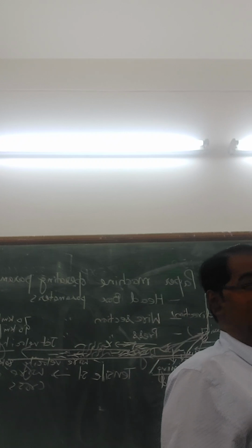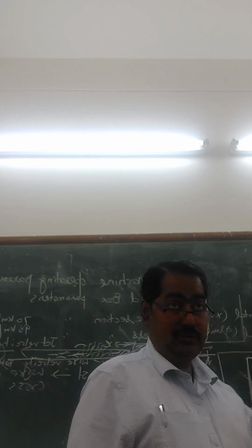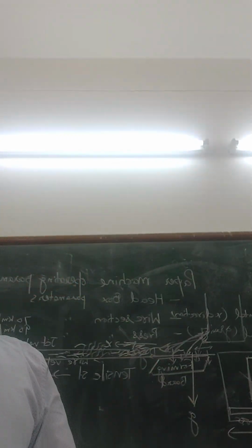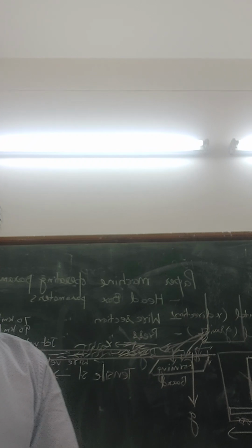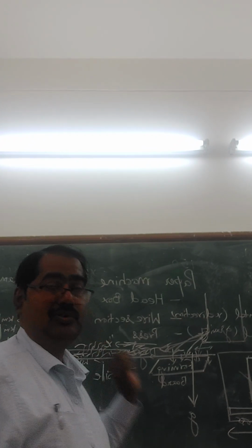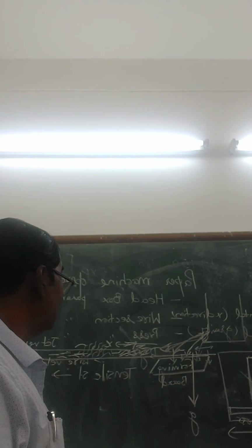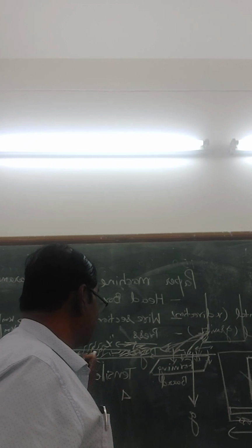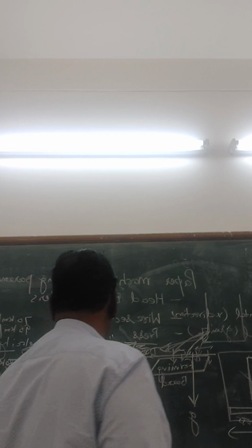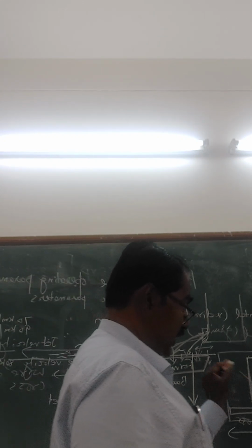So take for example, our task is to get higher strength in the cross direction. What can we do? We can decrease the difference between the wire and jet velocity. If we decrease the difference, that means both are moving at the same velocity.